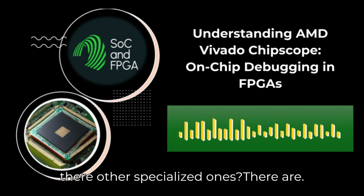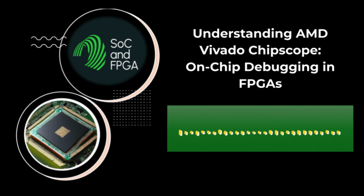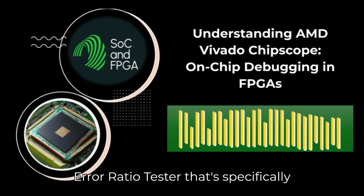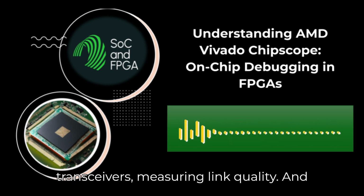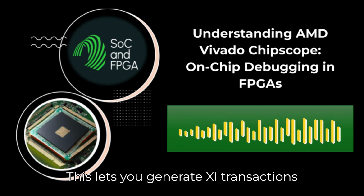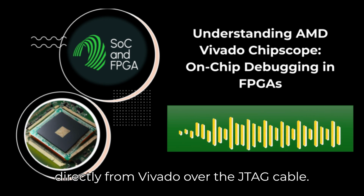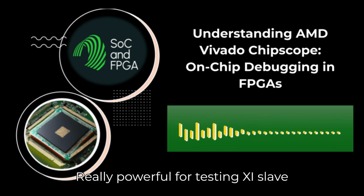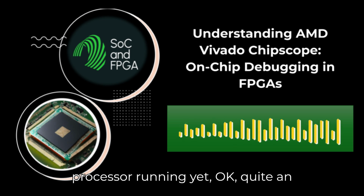Makes sense. Are there other specialized ones? There are. Briefly, there's the IBERT, Integrated Bit Error Ratio Tester. That's specifically for tuning high-speed serial transceivers, measuring link quality. And there's a JTAG2AXI master. This lets you generate AXI transactions directly from Vivado over the JTAG cable. Really powerful for testing AXI slave peripherals if you don't have a processor running yet.